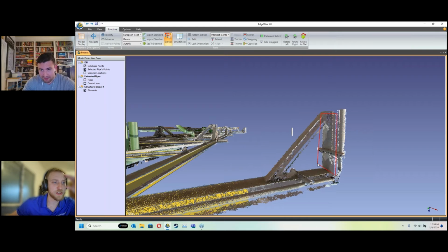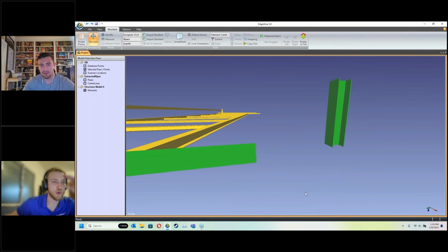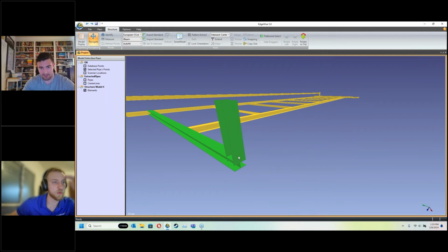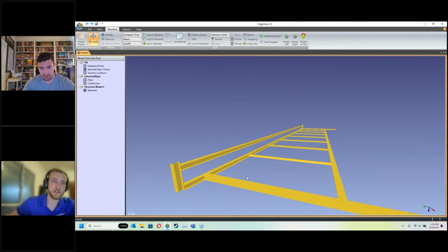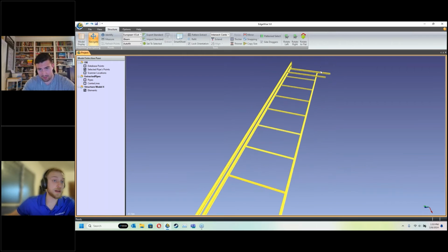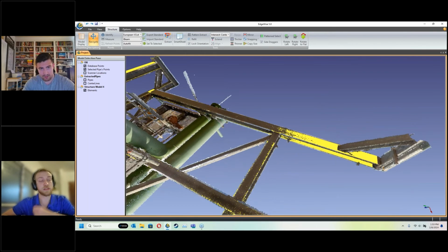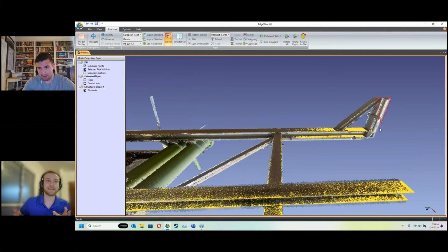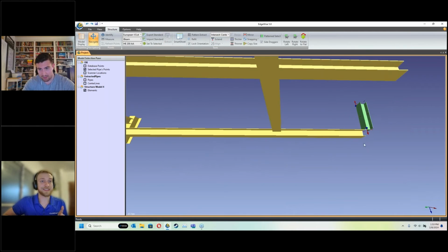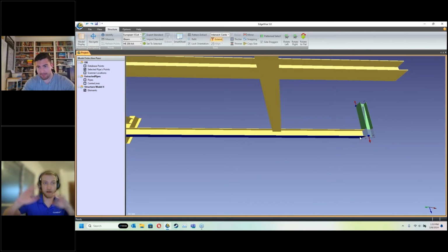We'll keep going with questions here. So the building geometry would be walls, just very stock walls. Insulated pipe panel, that's a good question. For insulated pipe, we are only able to see the outside diameter. It is possible for the user to specify the inside diameter of what the actual pipe is, but because the point cloud data only has insulation, we're going to initially draw insulation.